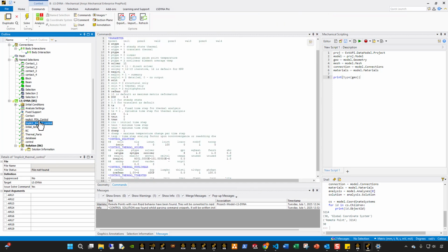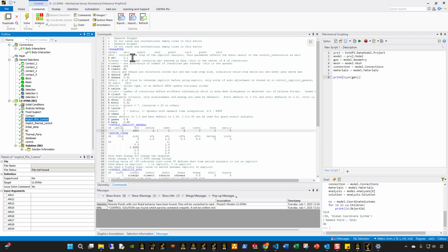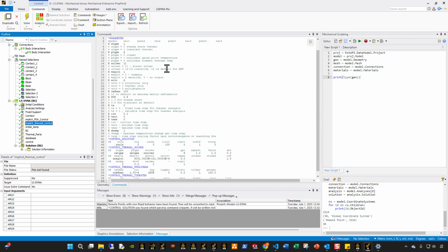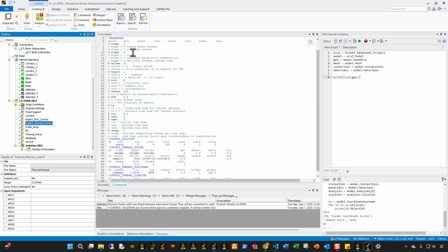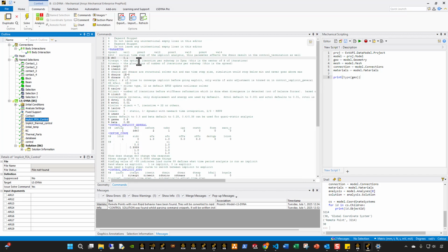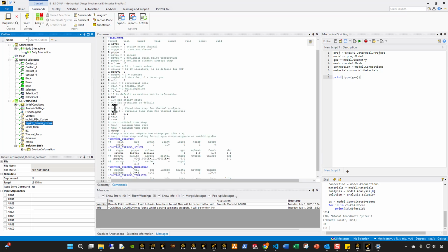By using a template, right? The challenging thing about a thermomechanical problem is that you actually have to control the solver behavior between the implicit structural side and the thermal side, right? For example, you see this delta T, this T0, right? You need to make sure they have matching time steps, right? So if you make one solver control have a much smaller time step than the other, it's gonna create problems, right? It's also related to the way the time stepping works, right?